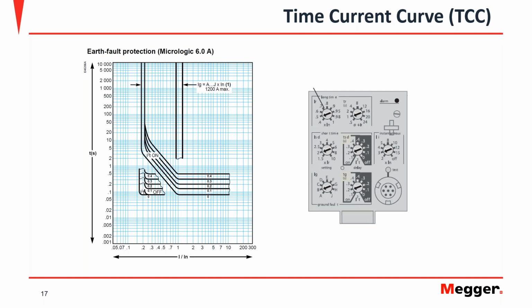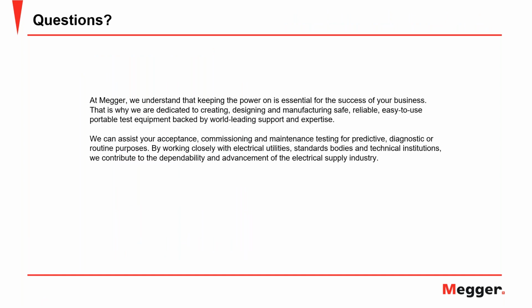Let me give a little background, so that we can understand the question better. Every instrument has a certain open circuit voltage, and the length of the cable going to the breaker and returning back, that whole circuit, one-way length, breaker contact resistance, and the return path of the return cable, all of this is the impedance connected to the test instrument.